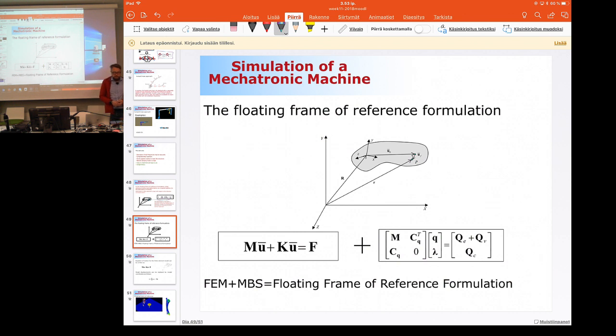In a finite element method, we have something very good to compute linear small deformation with respect to a reference coordinate system. This is exactly what we are expecting the finite element method to do here, because we would like to model the deformation with respect to this body reference coordinate system. And this is what you can do by using the simple linear finite element approach as written here. Here, of course, this should be u dot dot. So you're solving for the u dot dot, and you're introducing that to here.